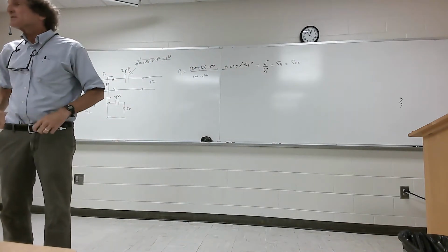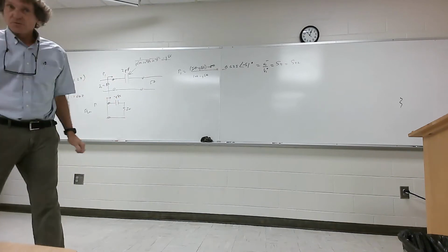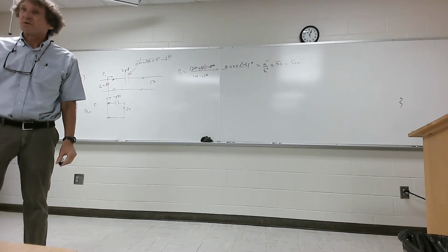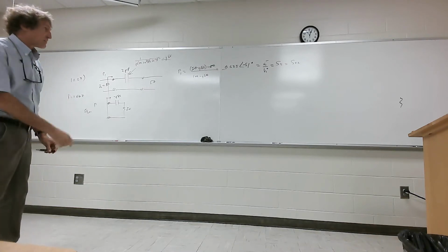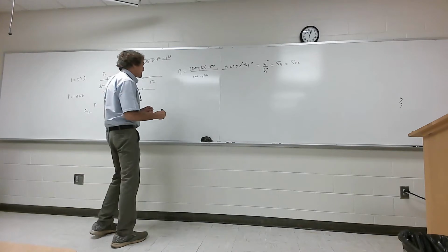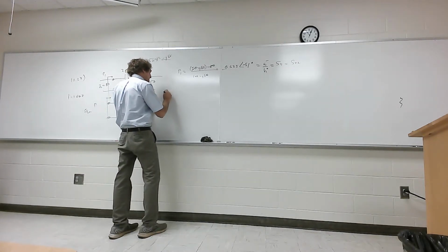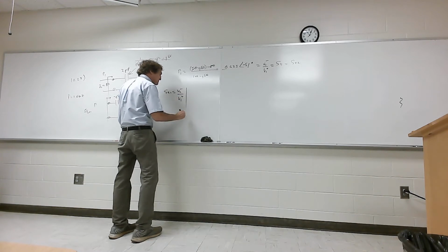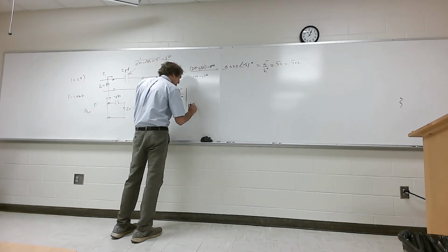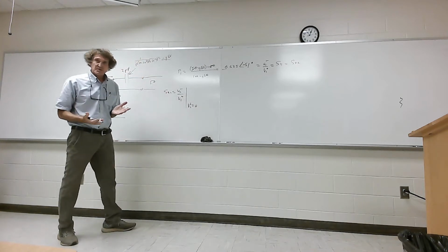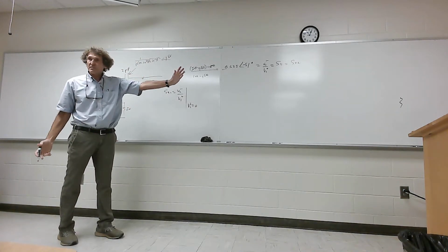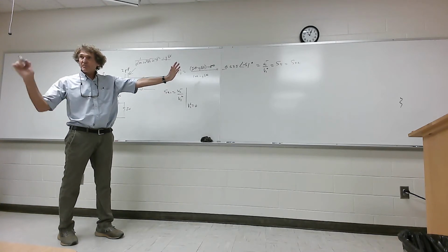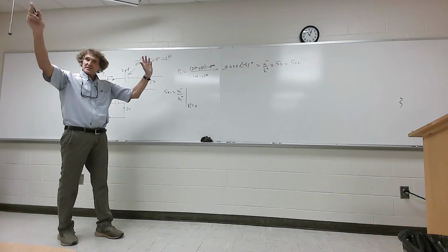Okay, now, next thing I need to do is find S21, and how many realize that will be S12? Everybody follow me on this? It's a reciprocal network. So S21 is equal to V2 minus over V1 plus, assuming V2 plus is equal to 0, it's just matched. If there's a 50 ohm load here, nothing's coming back and reflecting into that second port. Do y'all follow me on this, everyone? In the back, can you hear me and see me okay? I was worried about the guys in the back.